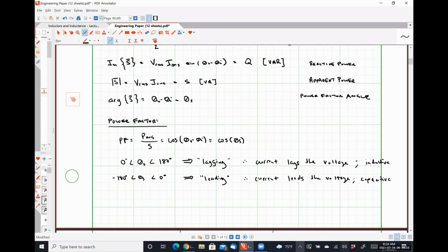For a power factor of -1, they're neither leading nor lagging because they are exactly 180 degrees out of phase. And for a power factor of 0, they're neither leading nor lagging because they're exactly 90 degrees out of phase. So if they're pi/2 or pi away from each other, or 90, or some integer multiple of 90 degrees away from each other, we can't tell which one is leading and which one is lagging. All right.